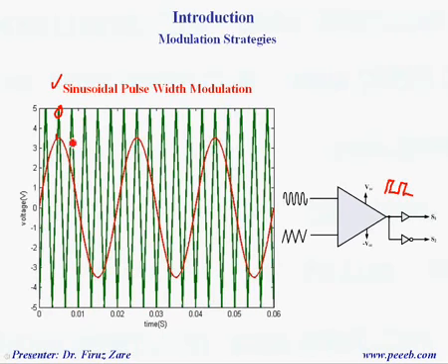So the point is that here we have switching frequency, which is defined, the switching frequency of this carrier, as I described before, is 1 over switching cycle. So by increasing the switching frequency, definitely we can improve the quality of output voltage and reduce the total harmonic distortion, but the drawback is we increase the switching losses.